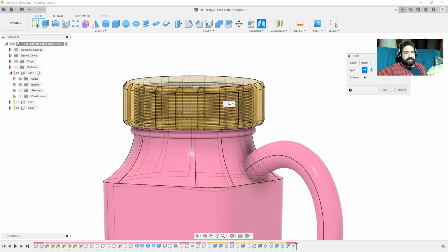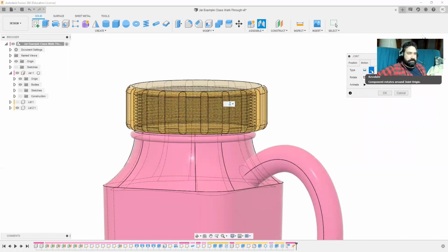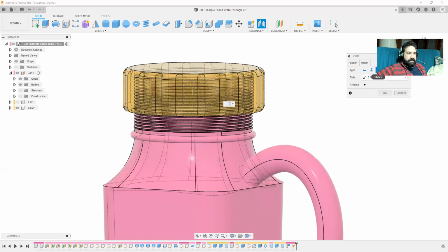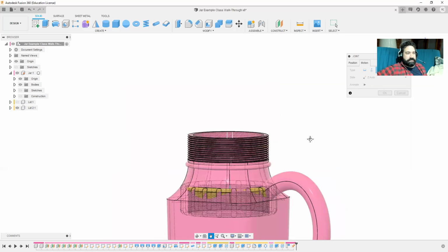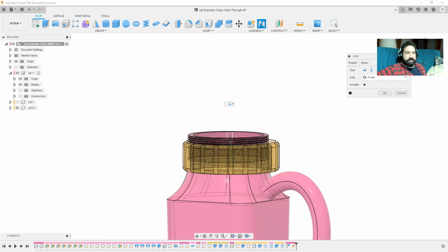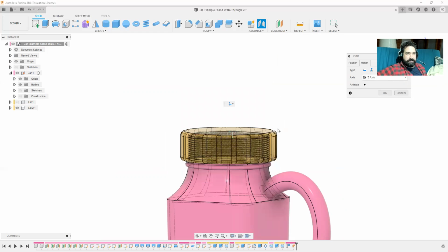And there's a bunch of options here. There's revolute, that's just revolving. There's slider, and this moves along a solid axis, kind of like a top hat. You can choose your different axes. Obviously, that doesn't work for this part at all. There's cylindrical, which moves it on an axis but also rotates, and that we might actually use.